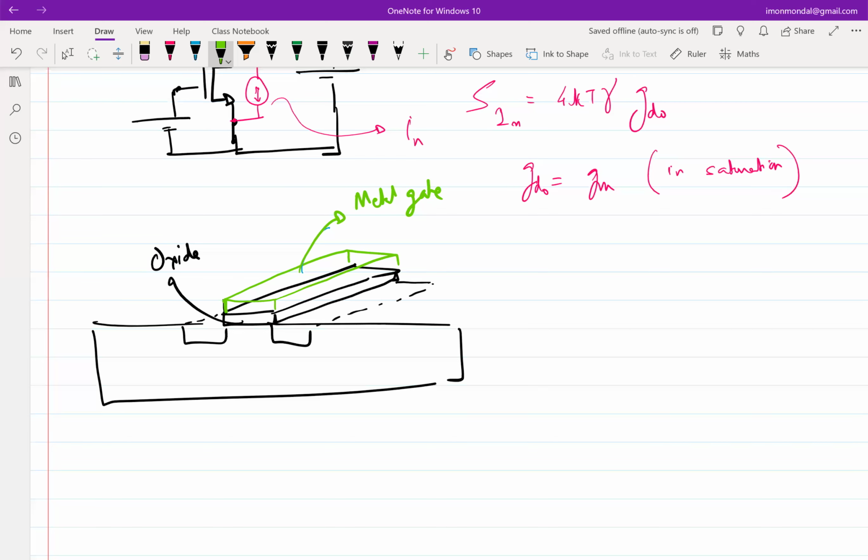The reason it is important is that polysilicon has higher resistivity than metal. But let's assume we are not bothered with that. We need a number, so let's say it is some material which has non-zero resistivity. Why is this important? It's important because when you connect the gate to anything, you'll not be able to connect the gate distributedly all throughout on top of the gate. You are going to make a contact. From the top of the chip, you are going to drill a hole that lands on the top of the gate or at the side of the gate.